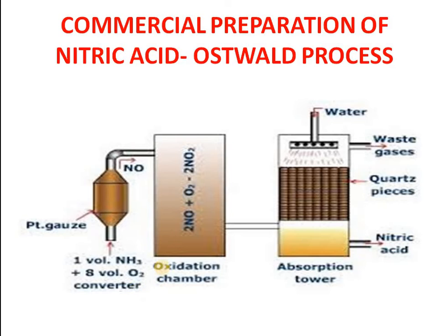Now NO is converted to NO2 in the oxidation chamber, and in the last chamber, known as the absorption tower, NO2 will dissolve in water. The waste gas is NO, maybe unreacted, and nitrogen will be there.